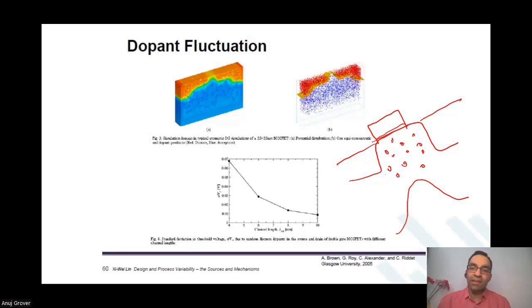To do the worst case analysis, you may say that, okay, I have to assume pass gate to be at 3.5 sigma, pull down to be at 4 sigma away. And that is my worst case. That was what we did in the SNM analysis, and in the write margin analysis also in the previous lecture. So we placed devices at the worst places and we saw the impact. But it is not that this is bound to happen exactly this way. We just want to be sure that statistically we are safe.